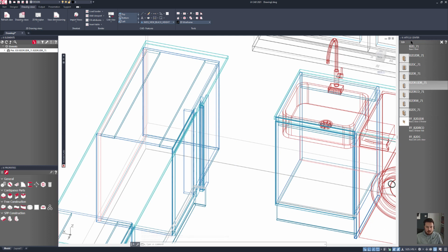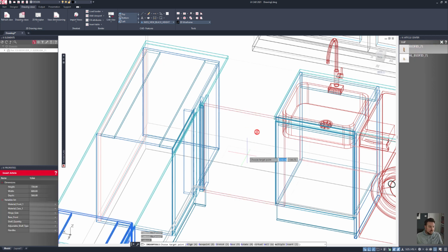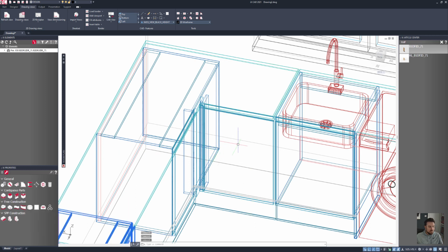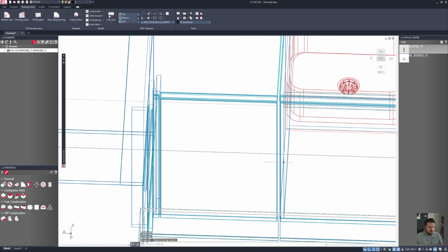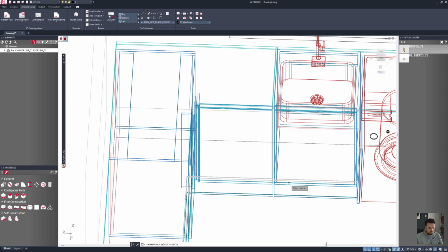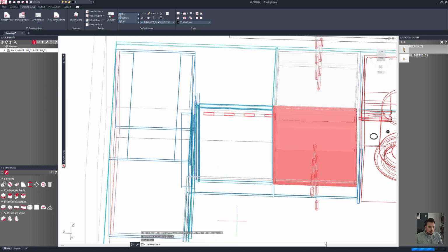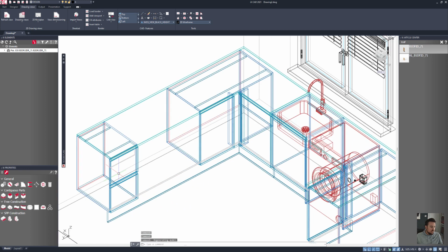So let's find my base one door fully integrated dishwasher panel, and then in here I need to just change that width instead of 600 to being 520, because that's the width of my custom dishwasher panel. And then in here I just need to nip that corner up a little bit, so again I can just use the stretch panel to stretch and say a difference of 8 mil in that direction. Okay, so I'm going to have to find somewhere else for my drawers, but that's okay.